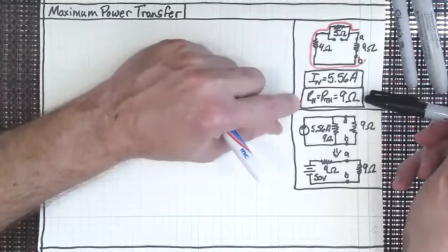And I also want to point out another thing. I said this at the beginning of the last lecture, it went for a long lecture, but I said, hey, I'm going to say that R sub L is 9 ohms now. And I'm going to say that for a reason. What I wanted to do at the end of that last lecture, although it went on a little bit too long, was to say that yes, this Thevenin's is 9 ohms, and the load is 9 ohms. Why do you think that is? And of course, that would lead me into today's lecture, which is maximum power transfer.